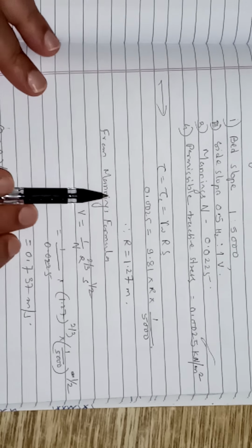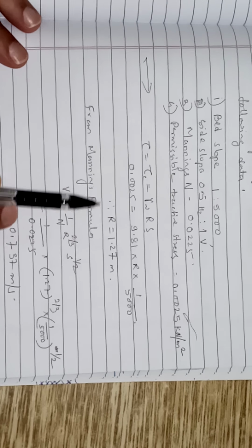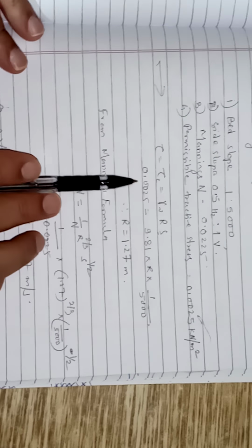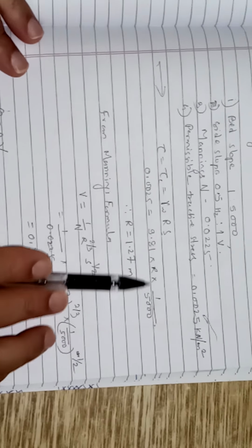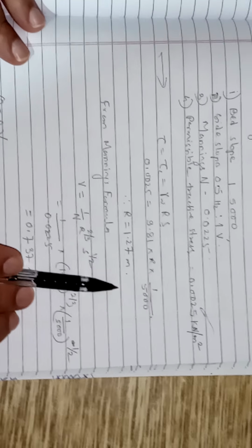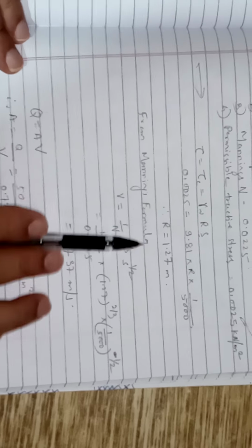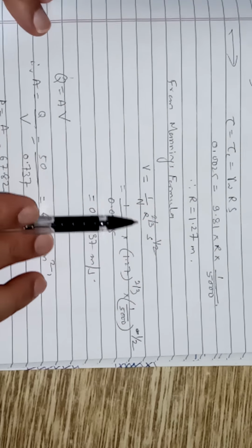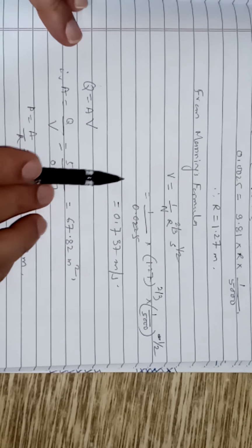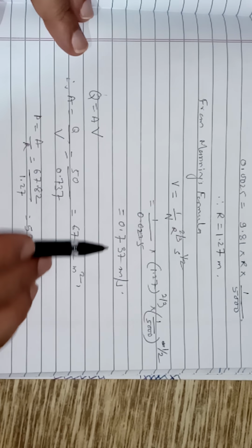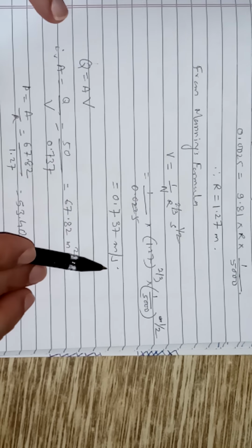So using the equation for the critical tractive stress tau_c = gamma_w R S, putting the value of tau_c, gamma_w and slope, the hydraulic radius R is computed as 1.27 meter. By using Manning's formula, V = (1/n) R^(2/3) S^(1/2), calculate the velocity of the flow, that comes out to be 0.737 meter per second.